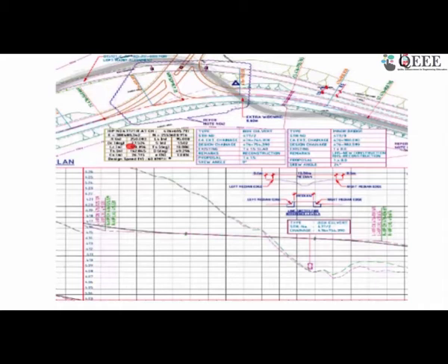It is much more prominent in railways, because the branch out can happen on the curve, whereas in highways we have better control and we don't want the branch out to happen on the curve but on the tangent sections, to avoid any negative super elevation. For super elevation, you normally need your outer edge to be raised. If, because of certain constraints, you are not raising your outer edge but raising your inner edge, that is negative super elevation.